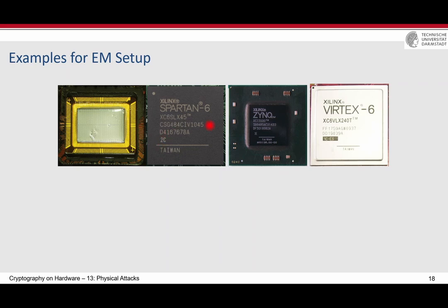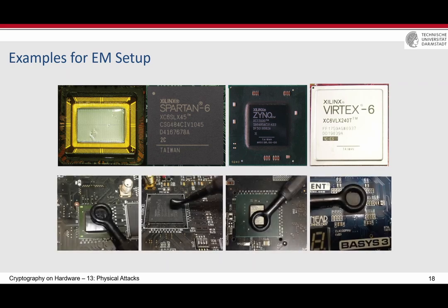You need to connect every pin of the package to every pin of the die. And here you see a metal cover over the chip. If you want to measure the EM, electromagnetic radiation of the chip, you can put the probe on top of any of them, but not here. Here is the metal package, and you have to remove the metal package. And here are some large probes, and one of them is similar to the chip that you have.